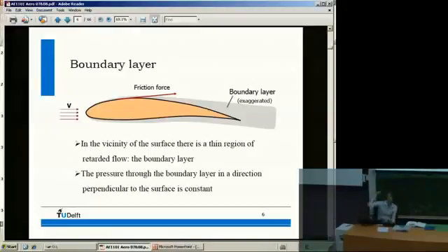And outside the boundary layer, the flow goes with sort of the flow that it would have if you don't take into account friction. And inside the boundary layer, a very thin layer, the flow is decreasing, from quite a fast speed outside to 0. And that is really the origin for the friction force.